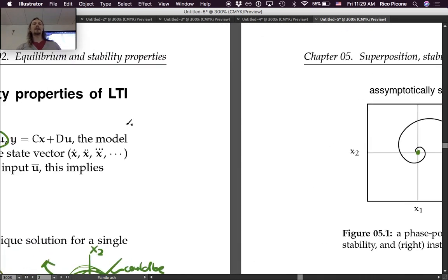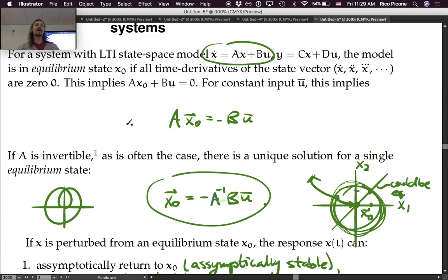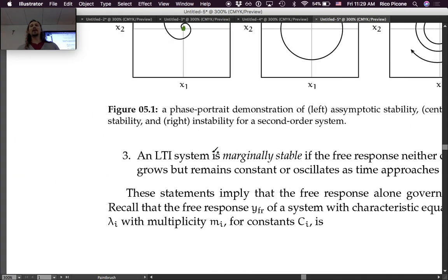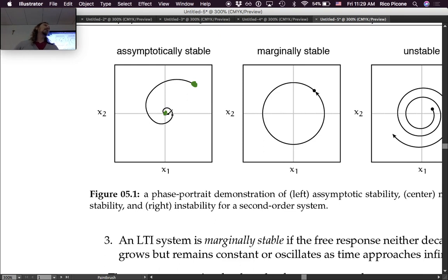So when no voltage is applied, what you have is this situation, but U bar is 0. So your x naught, your equilibrium point, is 0. So that's why it goes back to 0. But when you apply that voltage, the equilibrium point moves, right? So then it becomes whatever this is. You have to compute it. It becomes that, and so it decays to that new equilibrium point. So this equilibrium point is x0 if you have no input.